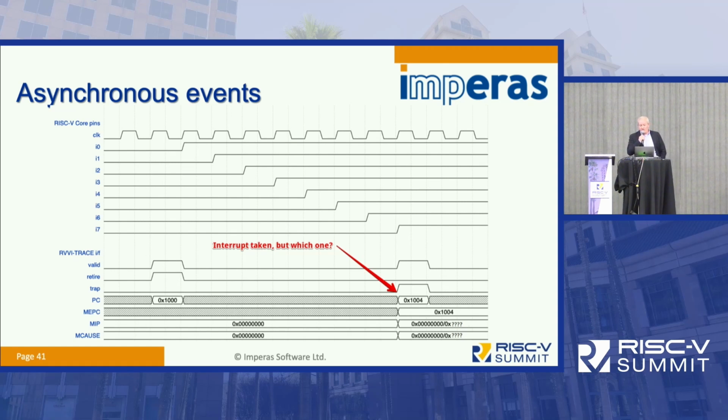But what you cannot predict is the latching behavior of those asynchronous events as they arrived from an architectural point. But what you can do is you can say, what are all of the legal outcomes? And you can use that as an envelope to say, these are the possible set of legal outcomes for this set of input events. And if the RTL produces something that doesn't fit within that envelope, then I'm going to flag that as an error.